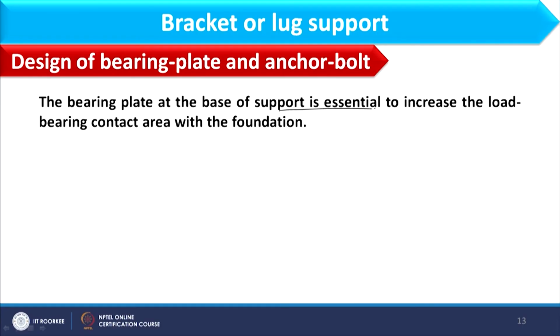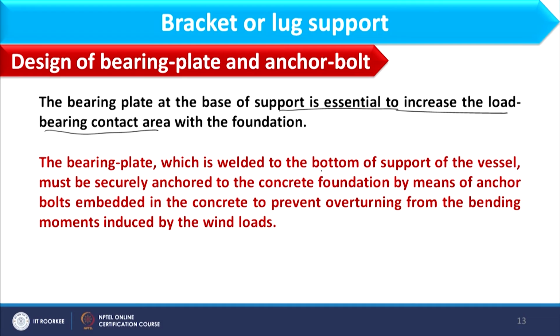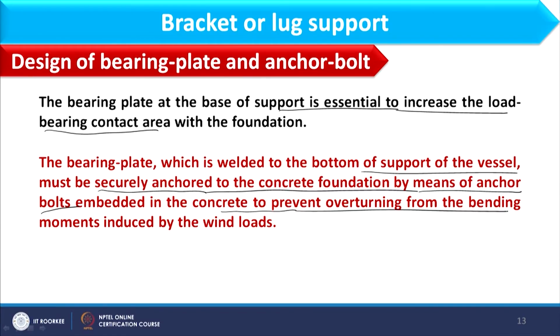So a bearing plate at the base of the support is essential to increase the load bearing contact area with the foundation. The bearing plate, which is welded to the bottom of the support of the vessel, must be secured, anchored to the concrete foundation by means of anchor bolts. What anchoring is and what an anchor bolt is, we will discuss in upcoming slides, so at present please bear with this. It is embedded in the concrete foundation to prevent overturning from bending moments due to wind loads.